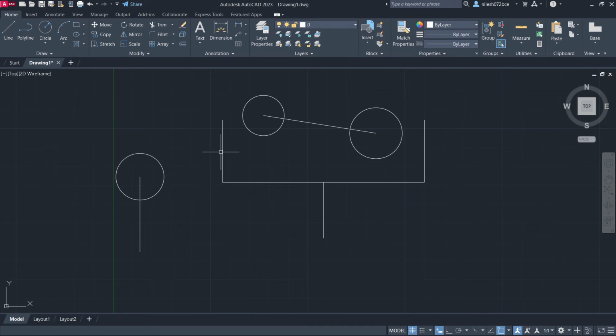And now let me delete all these lines, and again we will create these lines by turning the object snap mode off, and now this object snap mode is off. And now again I want to do the same thing, but what error will occur here is we want to create the line with the reference of the endpoints and the middle points. Let us see here. Now as it is saying, we can see this is the endpoint. I will press here and create a line.